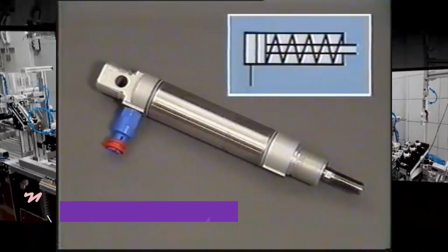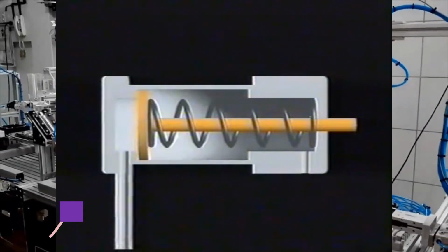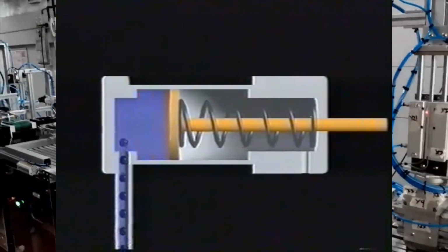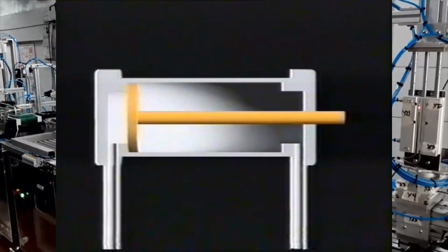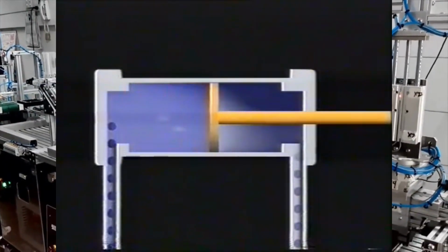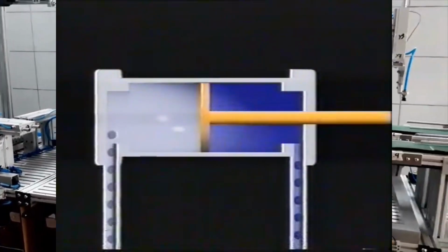Number 8. Pneumatic cylinders are typically used on industrial machinery and rely on compressed air pressure from 75 to 110 psi. Pneumatic cylinders are cheaper compared to hydraulic cylinders. Pneumatic cylinders offer more choices and sizes for easier integration into machinery.